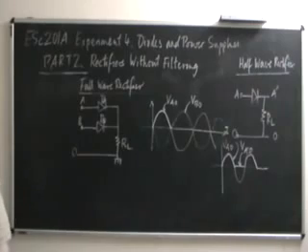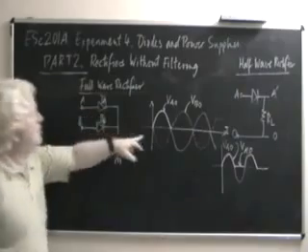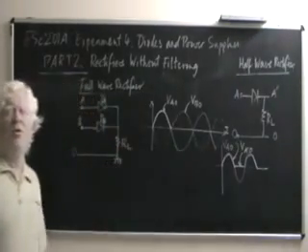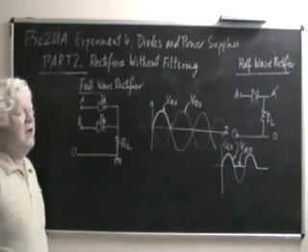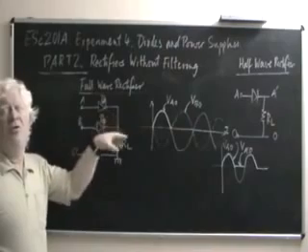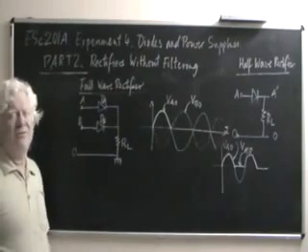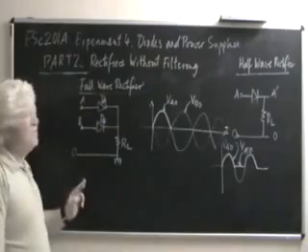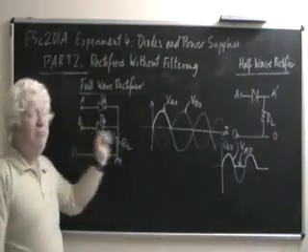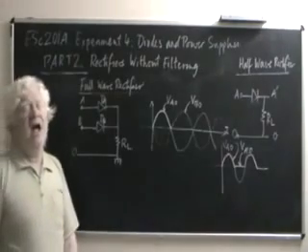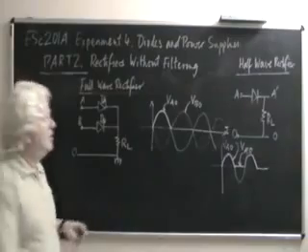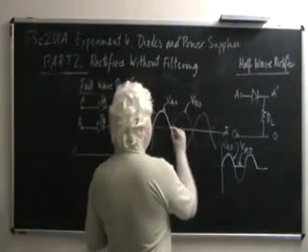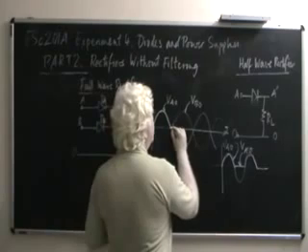What happens in the second part is that this diode stops conducting. In the second part of the cycle, the voltage of A is negative, so DA stops conducting, and so it is unable to contribute to the current in the resistance. However, at this time, the voltage of B goes positive with respect to O, and so DB starts conducting. And this conduction occurs for the second part of the cycle when A was negative but B was positive.